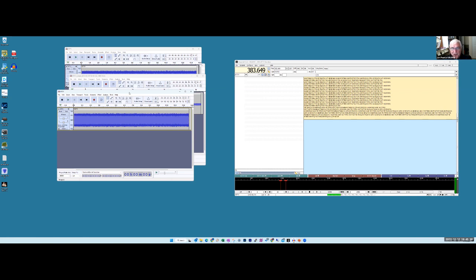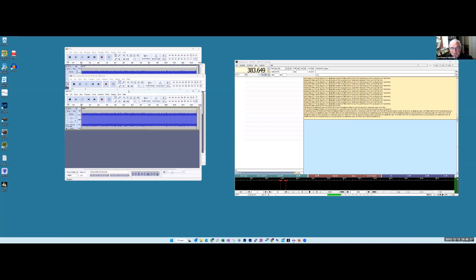I downloaded them, I dumped them into Audacity, and then I piped the playback into a virtual audio cable and piped it into MMSSTV, which is the TV decoder, and that's how I was able to get the pictures from the ISS that were recorded by the SatNOGS station. I did that over and over again for about a dozen pictures, and it actually worked. That's the only thing I've ever used this for, but obviously you can do all sorts of other really cool stuff with it.